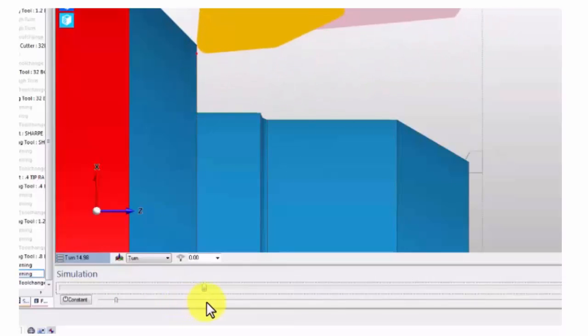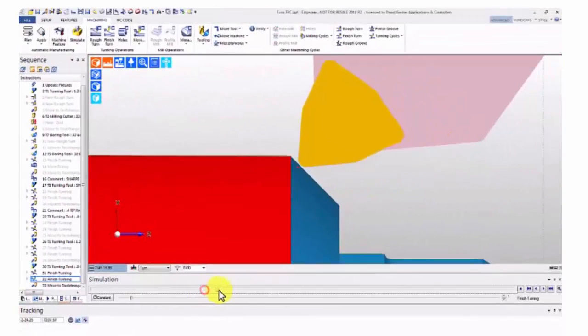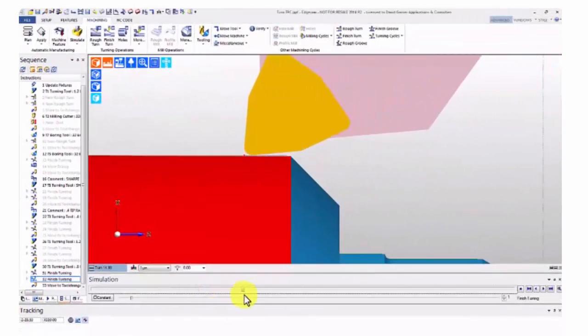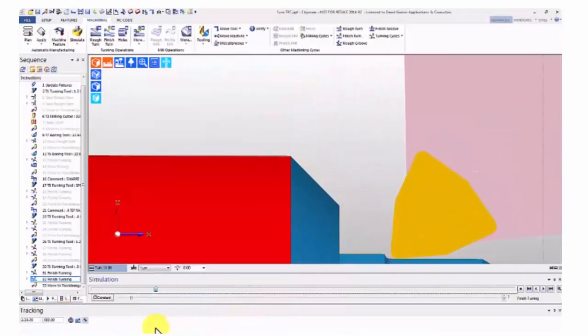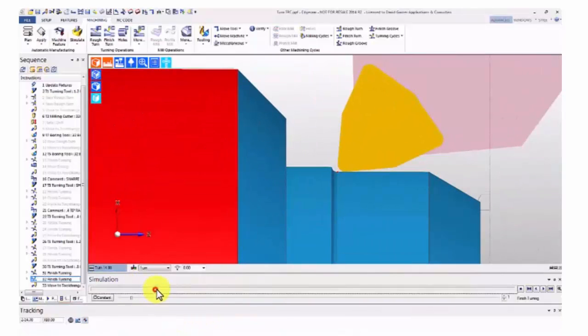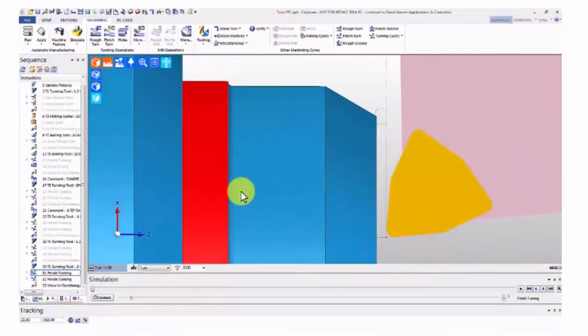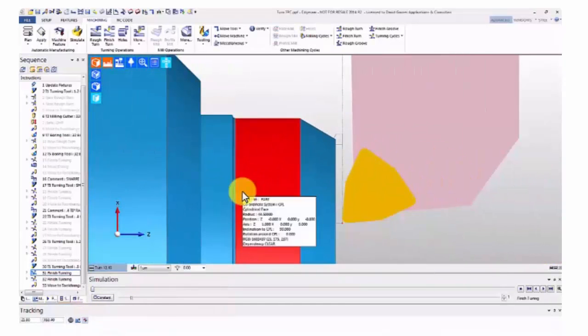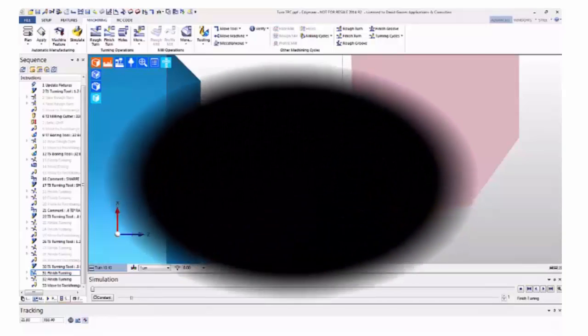So we're cutting all the while with the actual radius of that tip, and that's what happens in tool nose radius compensation. And if we change the radius of that tip, it would know, and as it's machining, it will still produce exactly the same path. So that's really why we would want to use tool nose radius compensation, because otherwise we don't actually get the correct cutter path, and it's very, very convenient.